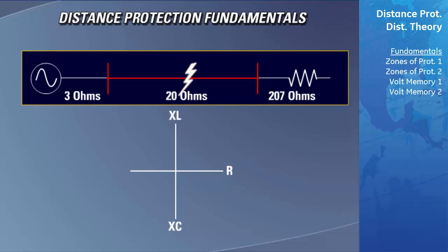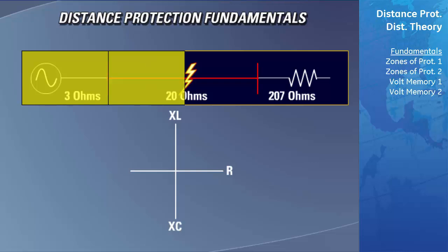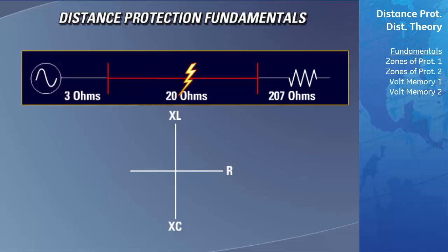If a fault to the ground were to now occur at the midpoint on the transmission line, all of the impedances after the point of fault would no longer be part of the power system. The impedance of the system would now only be the impedance of the source plus the impedance of the transmission line before the fault. The power system impedance is now no longer mostly resistive because the only impedance is now the mostly inductive transmission line. Therefore, the plotting of the measured impedance on the RX diagram will be very close to the y-axis.